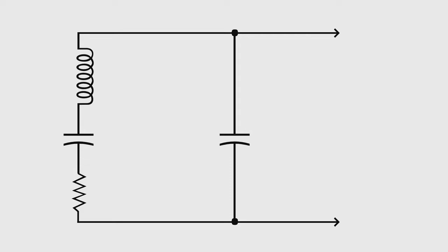That's good because all this together makes a real high Q circuit. If there was a bigger resistor, the Q would be broader. This thing wouldn't resonate right on a particular frequency and hang there like crystals do. The capacitance in parallel with it, the shunt capacitance, represents the electrodes or the leads to the crystal and any stray capacitances that are in there. So really it's just an RLC circuit. Make more sense now? A little.